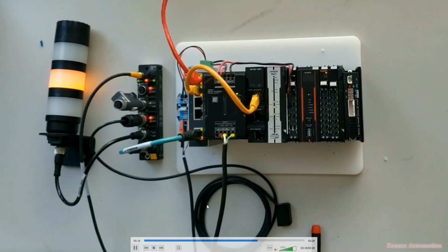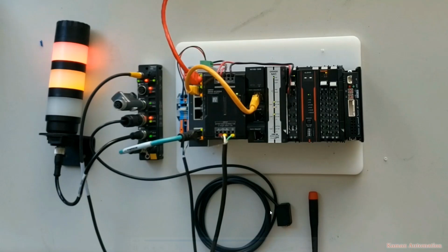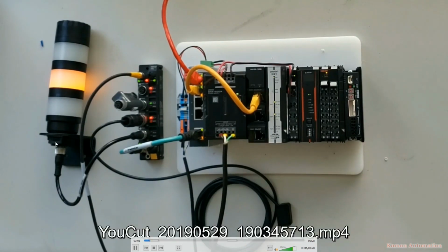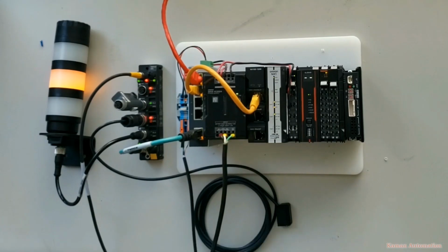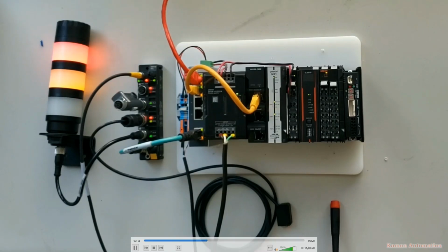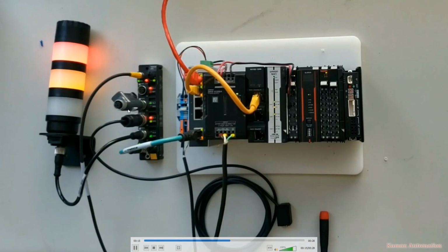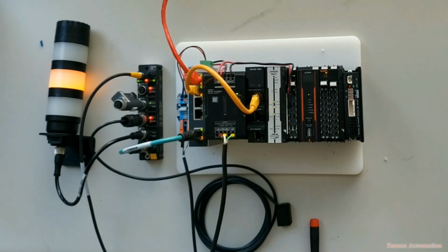The first is this Omron Photo Eye IO link sensor, series E3Z. Over here we have a Banner TL50 light stack. This stack is connected only by digital outputs to view the invocation status of our controller. And it won't be used for the purposes of this demonstration, but over here is an analog interface module from Phoenix Contact. It converts an IO link port into an analog output signal. For example, this one is 4 to 20 milliamps for use with other control systems.